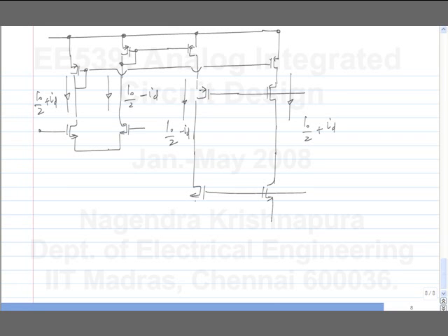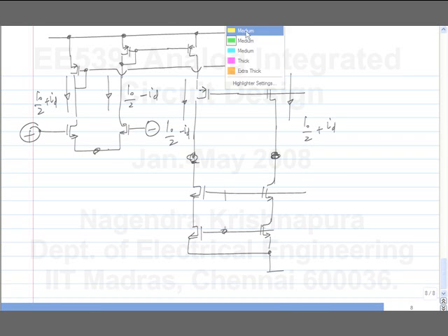So you can see that very quickly you can get very complicated circuits. Actually, let me not do this. Let me not show these connections first. That's why I wanted this to be the plus terminal of the op-amp, this to be the minus terminal. Now on the bottom I have drawn the cascode. So which side will I mirror from which side? There are two possible terminals for the output, this one and this one. Okay, I can mirror from this side to this side or from right to left. Which side will I do so that this to be the positive input of the op-amp and this to be the negative input?